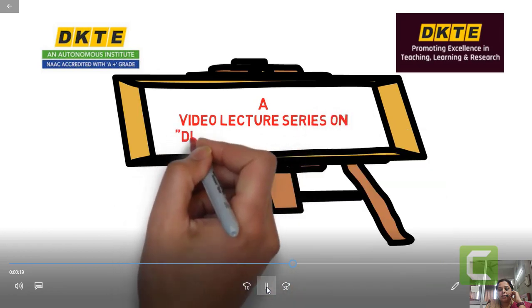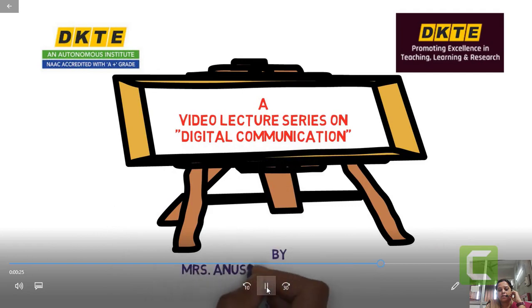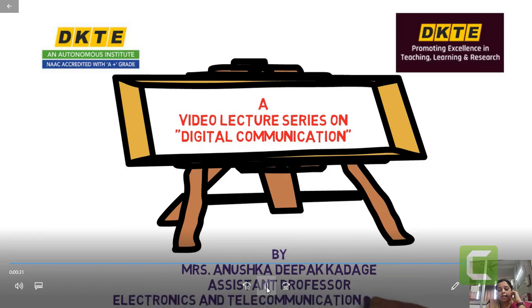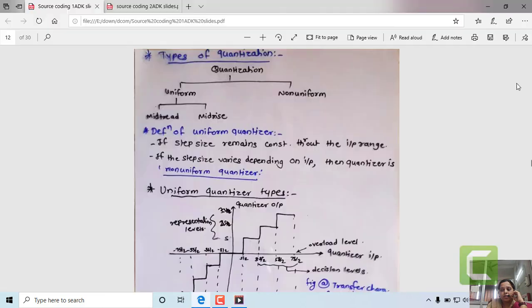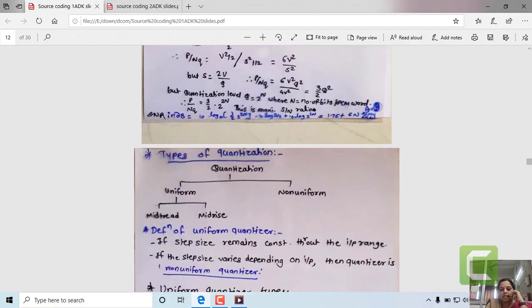In the previous lecture, we completed the derivation related to the SNR of the PCM system, where we concluded with the equation SNR for PCM equal to 1.76 plus 6N, and we commented finally that for every single bit increment in the PCM word, the PCM SNR value is going to increase by 6 dB. With that conclusion, we stopped in the last lecture.